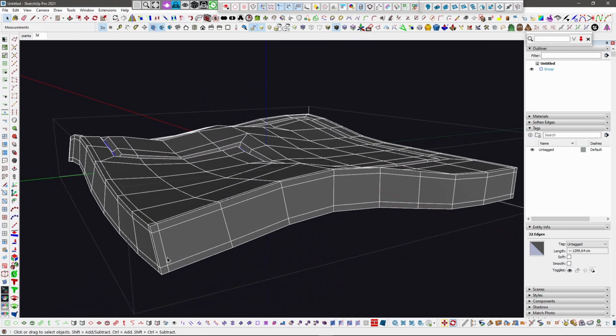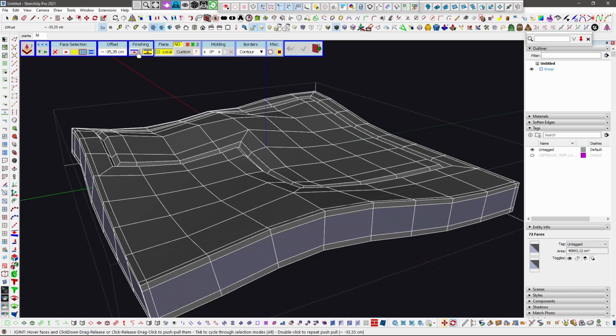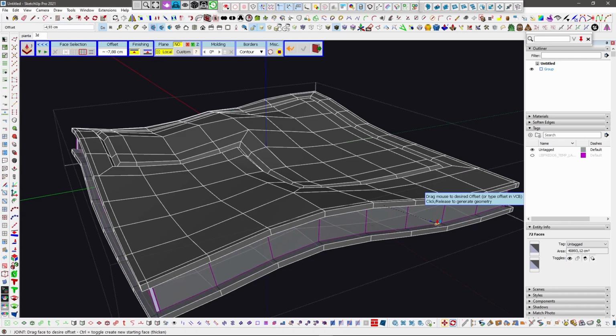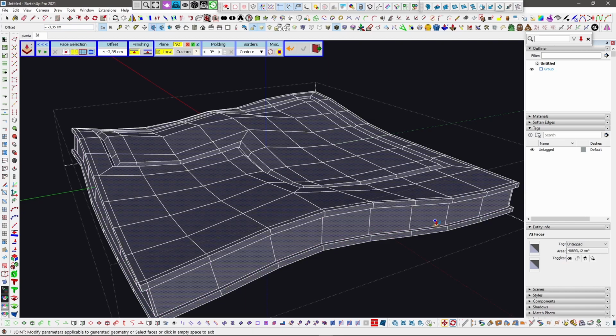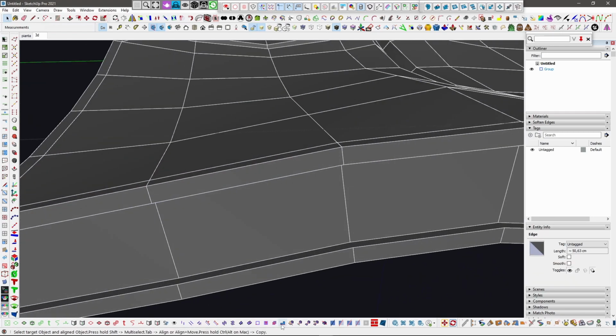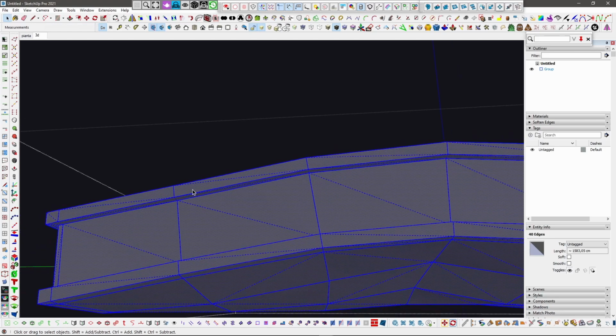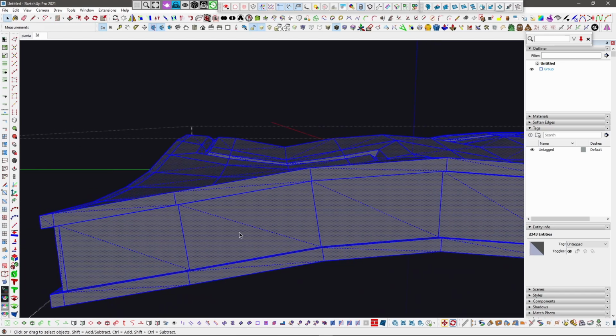And maybe also I want to take this and just crease this for subdivision. I type in 1S, and also maybe I can create some groove here, and this time I don't want to add thickness to my joint push pull, and do something like this, and take this loop and this loop and crease them. So again 1S, and again I want to unsmooth my quads, make sure they are compatible, and maybe triangulate all of this.